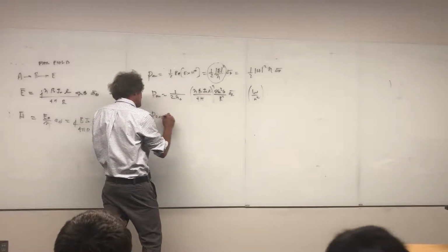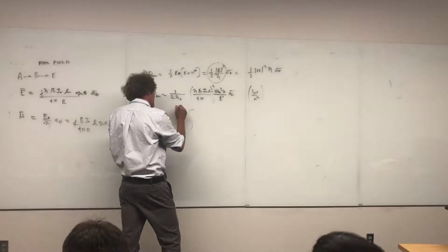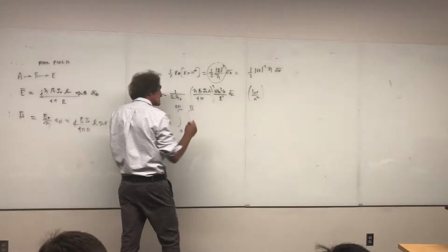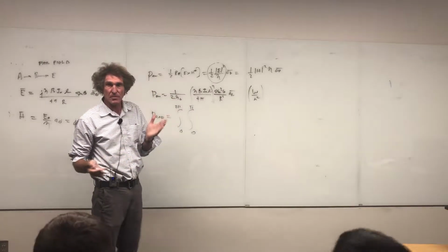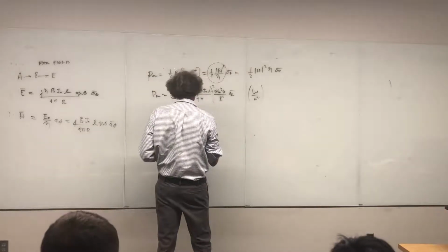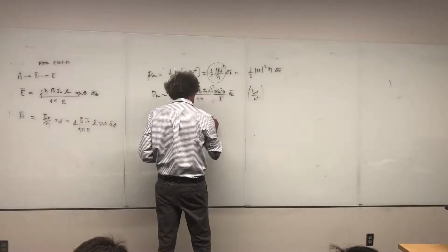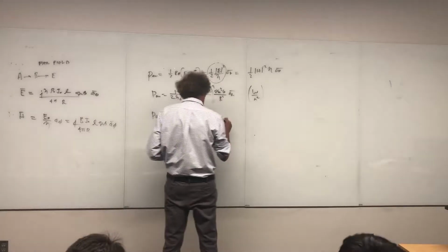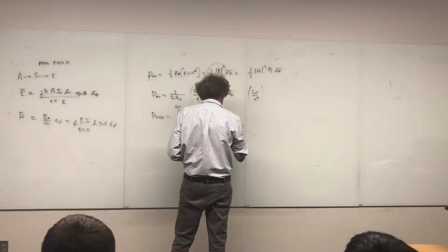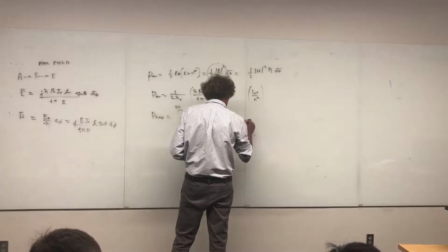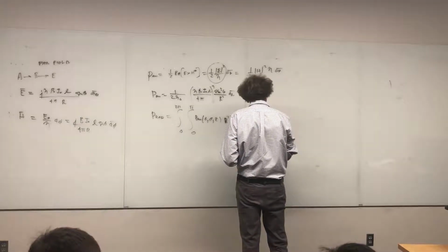Now, the total power radiated, right? P radiated from a short dipole would require you to integrate from 0 to 2 pi and from 0 to pi. This is a review, by the way. We did all this already. I'm bringing up the speed so I can go to where I'm going today. Then it would be P av, as a function of theta, phi, and r, times r squared times sine theta d theta d phi.